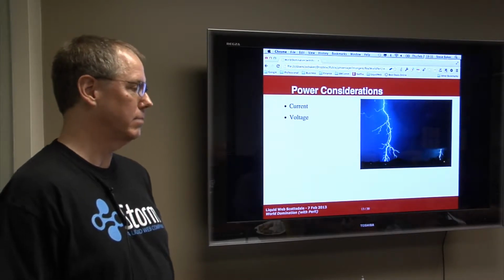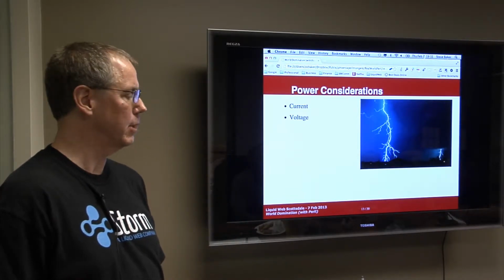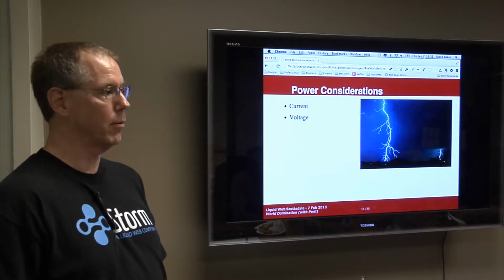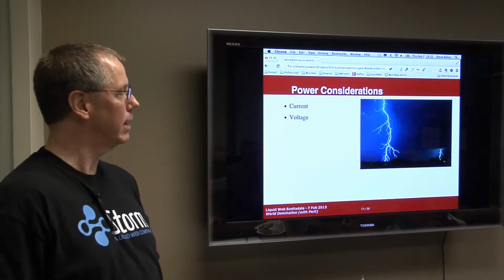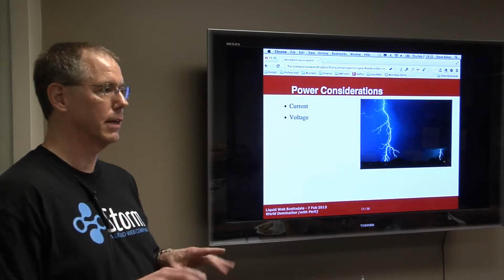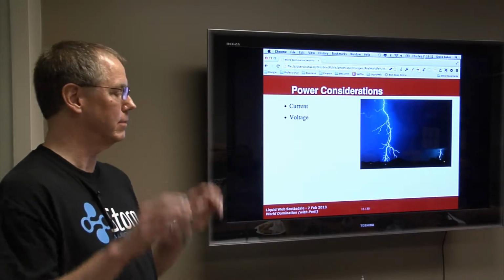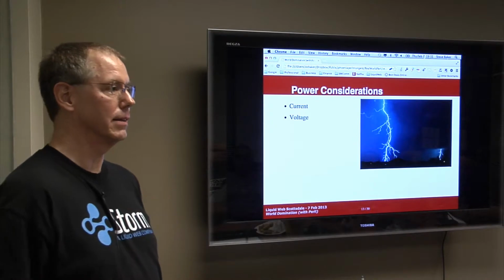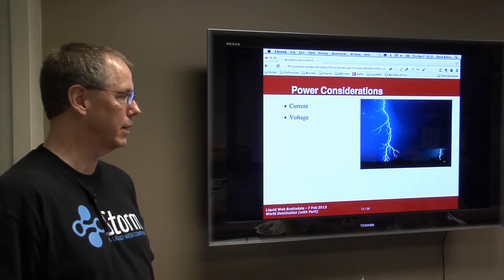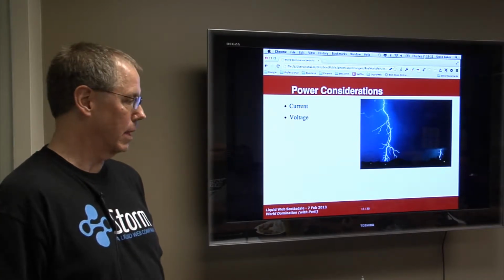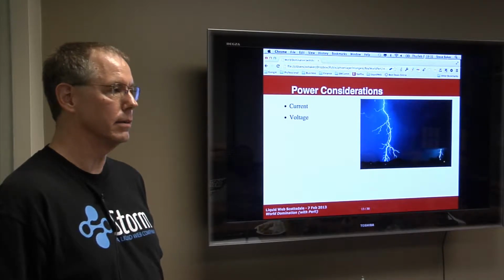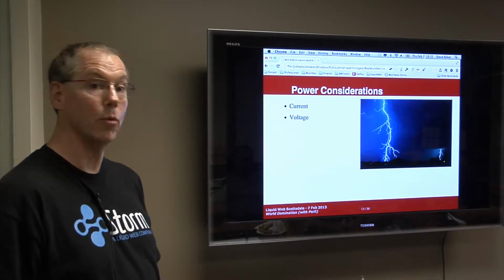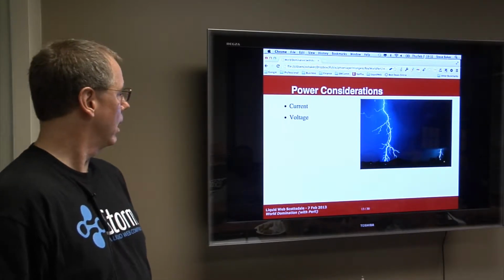You can plug it in on your USB port in your computer. It might work. I plugged it in to mine. It worked until I started typing, and then the keyboard would start acting really strange. It'd start repeating keys, and the problem turned out to be the power. So I stuck a 1 amp power supply on mine and run it off of that. Works much better.